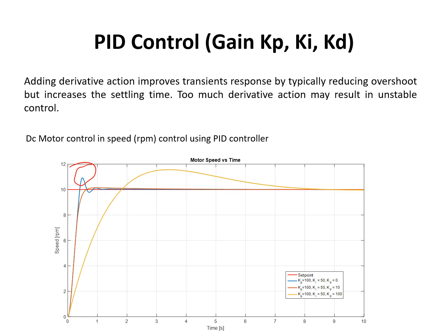And again, if we now increase the derivative term, we can see that it becomes a much slower response of our system. So again, there is some sort of compromise between having a much higher gain for each of these systems.